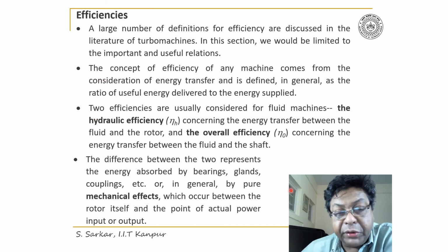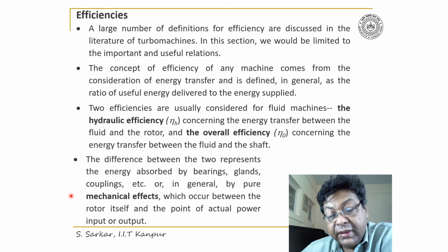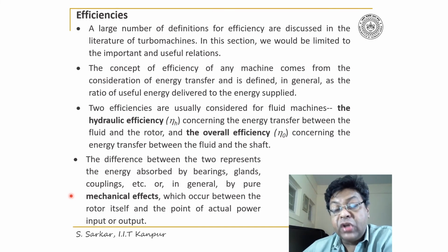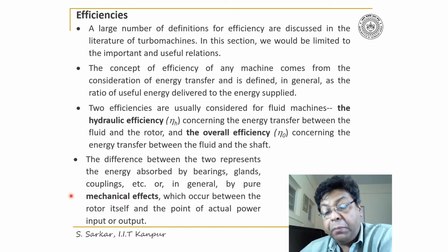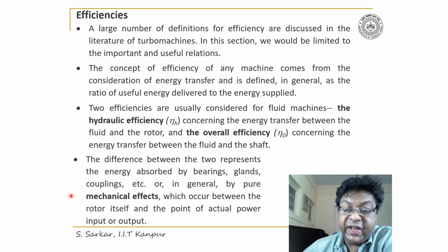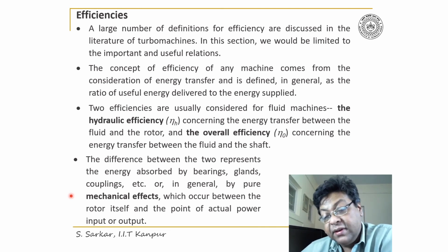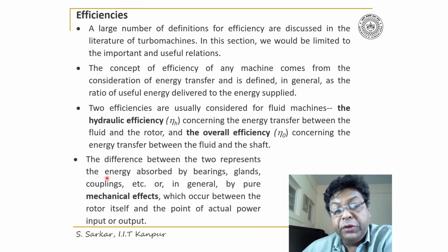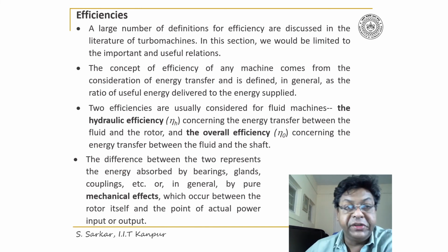Thus, the difference between the two represents the energy absorbed by bearings, glands, couplings, etc. That is, in general, by purely mechanical effects. And thus this difference between the two, that is overall and hydraulic efficiency, dictates the mechanical efficiency.